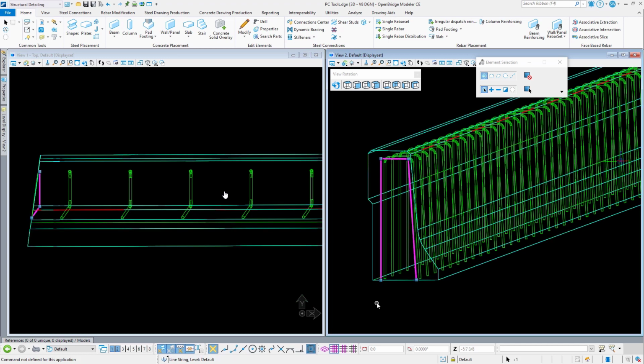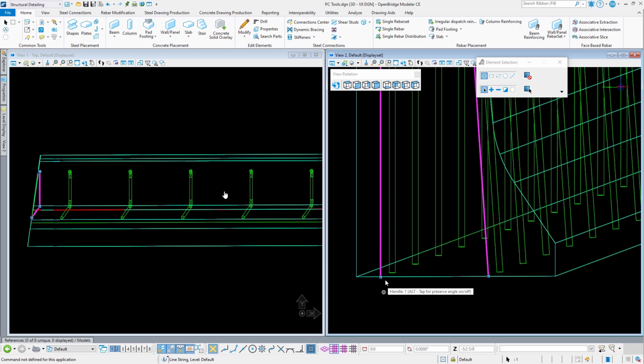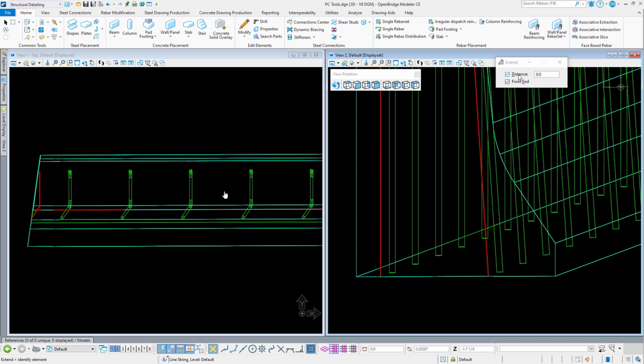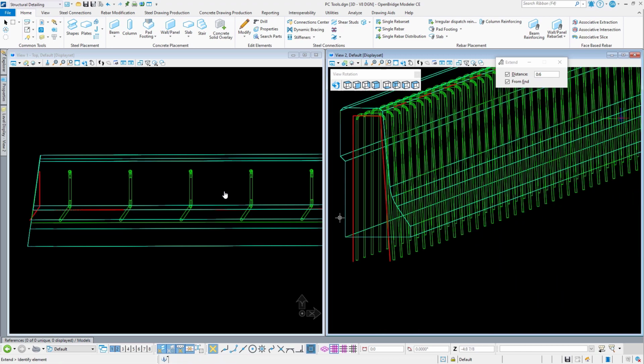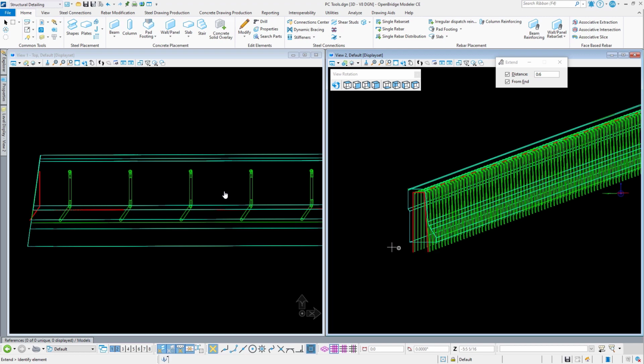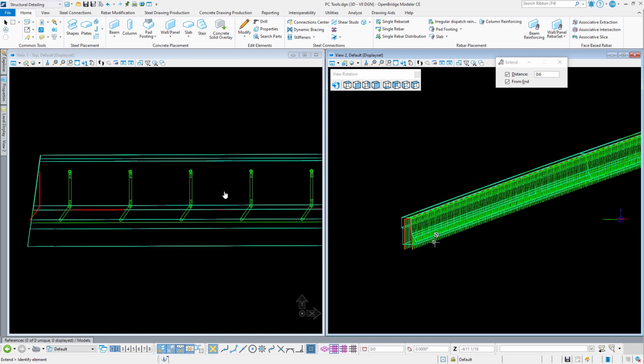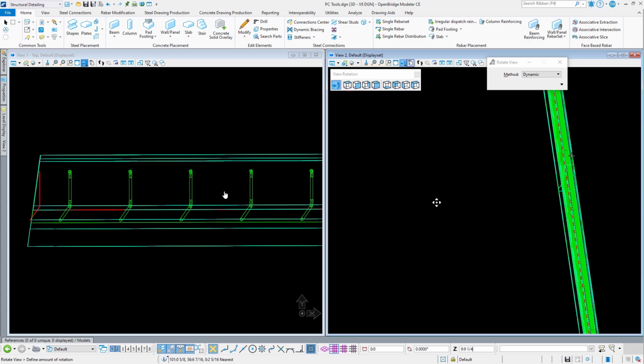And it will always honor that shape right there. So if I were to come in here and modify this 3D smart line, I could come in here with the extend element or extend line tool and maybe project it down 3 to 6 inches down into my concrete deck. When I do that, all the reinforcement that was modeled relative to that line changes as well. So we can see that it's updated all of the bars here relative to that one 3D shape.